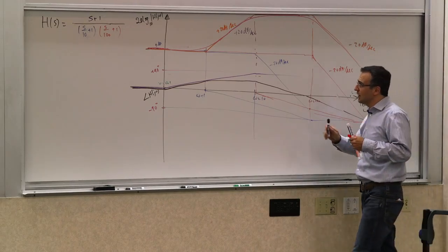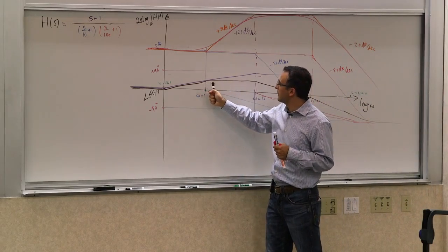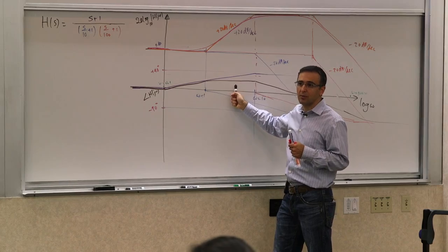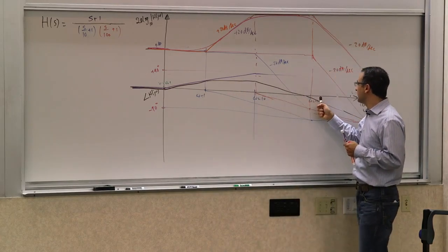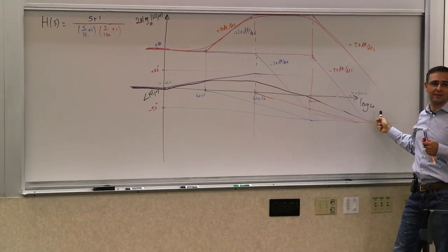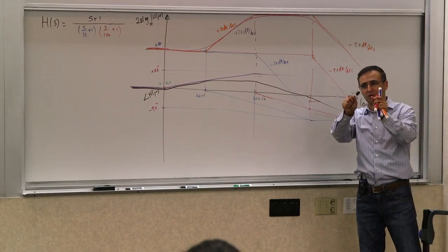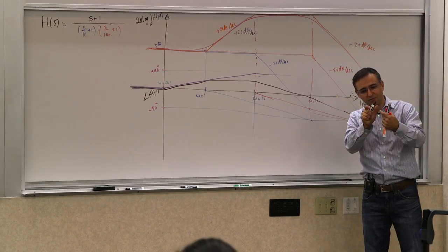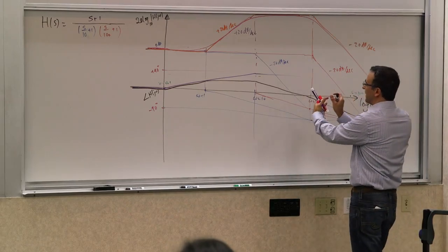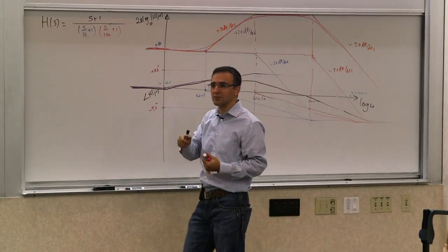So that tells you that as the amplitude is increasing, the phase also starts leading first, becomes positive, and then it goes back to 0, and then it goes lagging. If you look at the phases of the sinusoids, you will see that for a system like this, the output starts getting ahead, and then it goes back and falls behind as you increase the frequency.